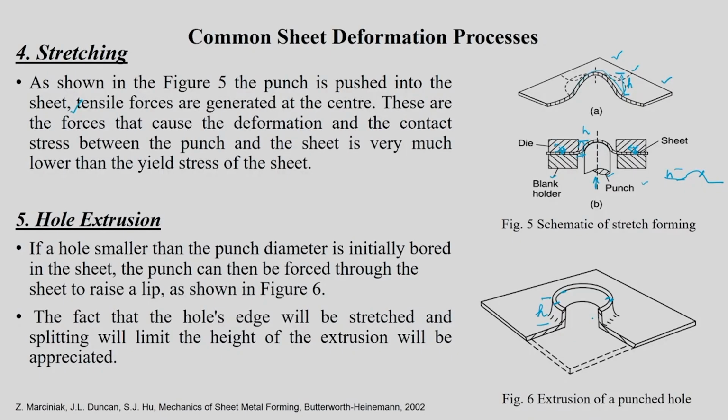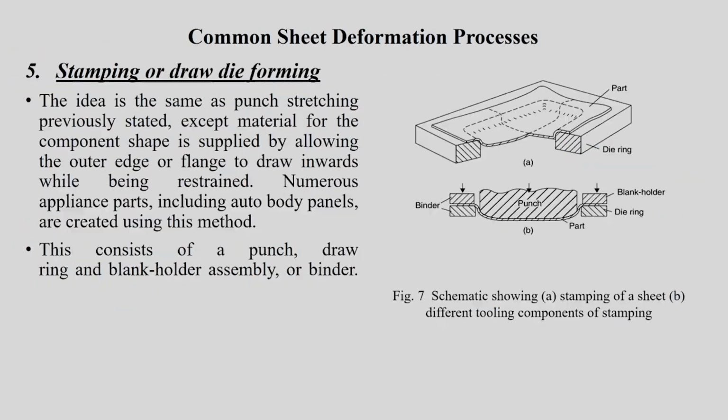Depending on this, one can select the material responsible for making a good material which is useful for making that kind of components. So I have just written here that the splitting will limit the height of extrusion. The larger the height, the better, but at the same time you should be able to make the whole stretching operation without any problem. That means a fracture should not happen at the edge region.